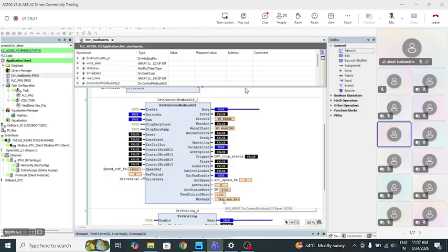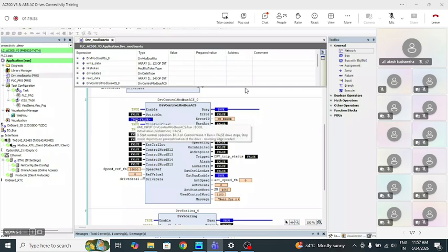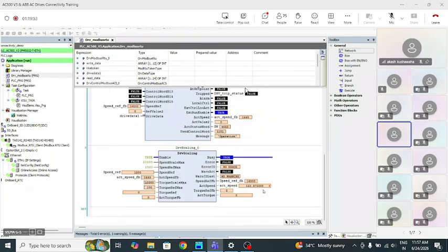So here, once you reset the fault, this also has to be on and off. Okay, so this I'm showing directly, but you need to create a logic. Whenever there is a fault, these two inputs have to be reset again. Okay, so again when I start, the drive will operate. So this is how very easy it is to communicate ABB drives and ABB PLC.